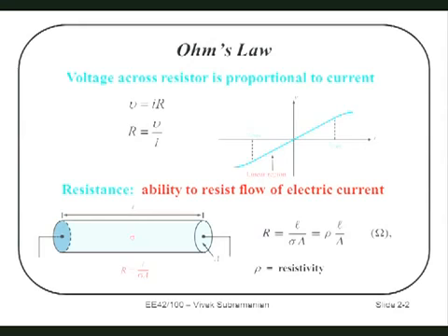So I would expect then this to be less resistive. Okay? Now we get to define a property, and the property we get to define is resistivity. Resistivity is a property that describes, in a unit cube of material, what is the resistance. And if you know what the unit cube resistance is and want to find the resistance of something that's not a unit cube, you just multiply by the length, because the length increases resistance, and you divide by the area, because area reduces resistance.